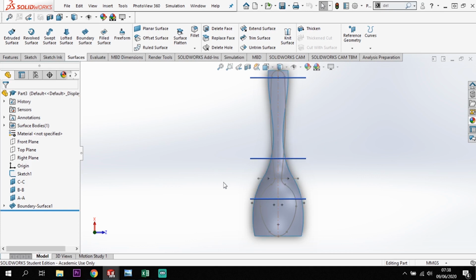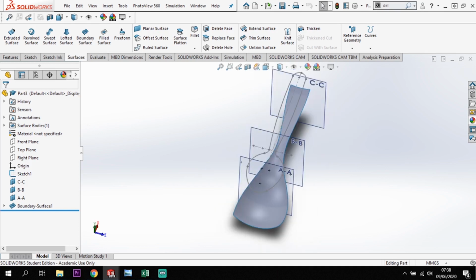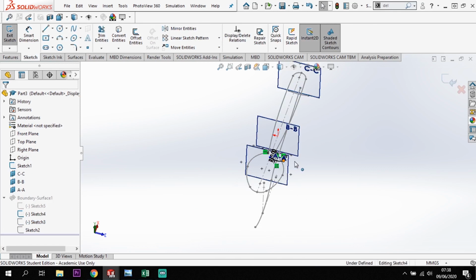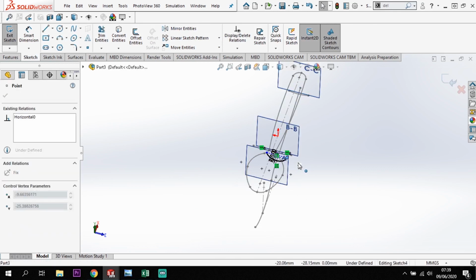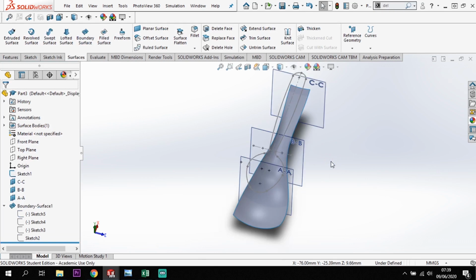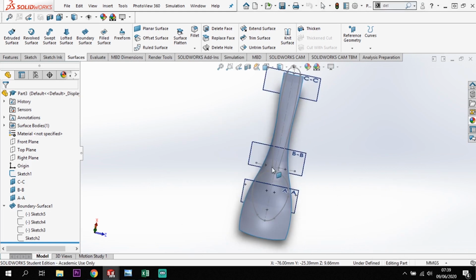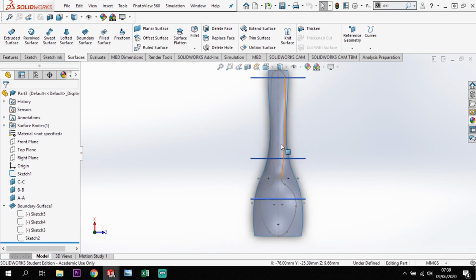So what I might need to do is extend some of the lines that I've been drawing there, which we can do no problem. All we do is come back into here, and we go into the sketch, edit the sketch. I just need to drag that out a little bit more. You should see the profile change. Now again, if we go back to the top view and now we can see that it is just outside, so we're perfect with that. So that's just a little bit of an editing process until we know we've definitely got the shape that we are after.